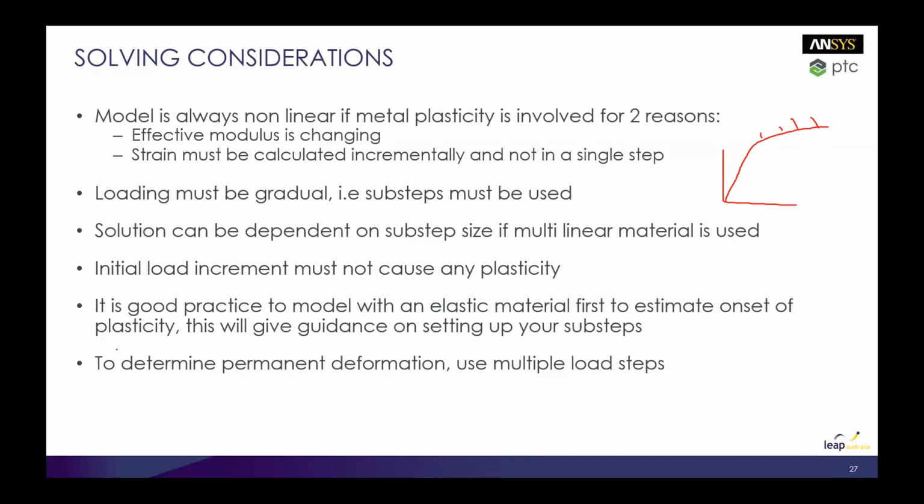Okay, so whenever you've got material plasticity, it's always a good idea to first model with a perfect elastic stress. Then you apply your force, and you know what sort of stress levels you're getting. So you might wind up here in the end. You know that when you're first loading, you want to be down in this region here. The solver will automatically substep, but sometimes you might need to go smaller than that substepping. So it helps you to set your first initial substep.